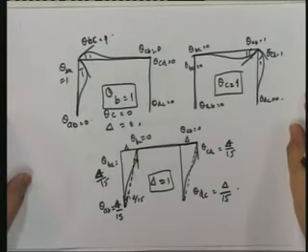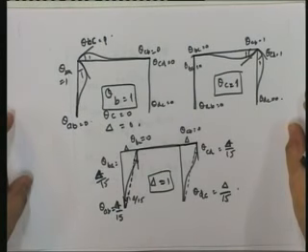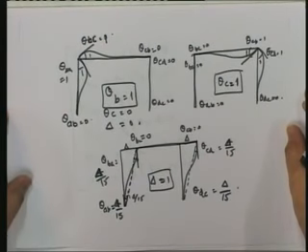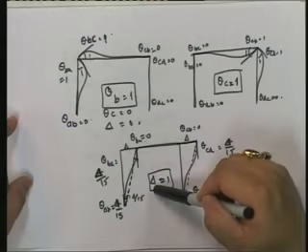So that is my virtual work equation, and that virtual work equation is what is going to give me the 3. And since I have 3 independent, I will get 3 independent equations. If I get 3 independent equations, I can solve for the displacements. I have 3 equations, 3 unknowns, I can solve for them.